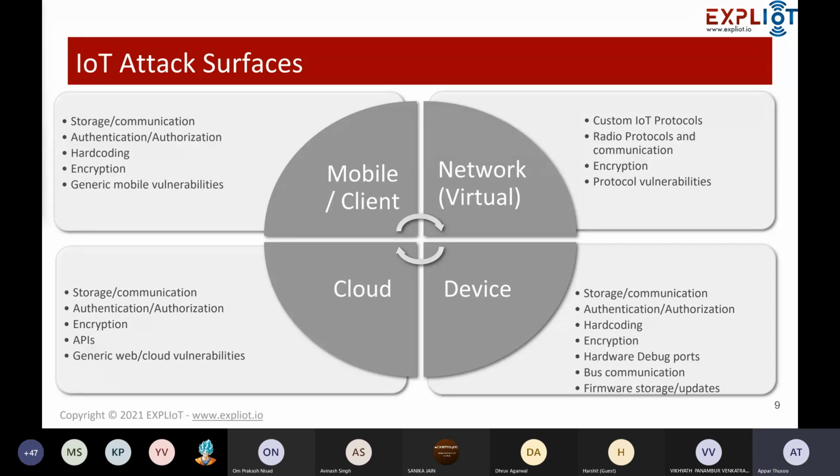Talking about the device itself, you have a lot of different attack vectors that you can explore on the device. This comprises your storage. By storage, I mean the flash memory on the device PCB. The communication. Again, by communication, I mean the onboard communication, using protocols like I2C or SPI for inter-chip communication. Then you have your authentication and authorization.